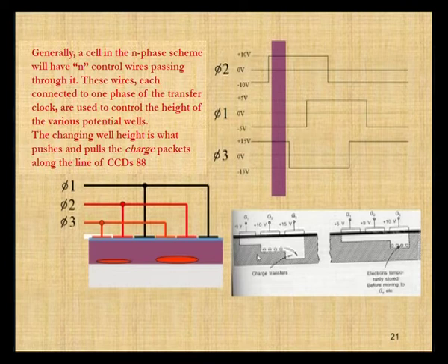The picture also shows clearly how the charge from phase 1 is moved to G2, under phase 2, where the charge is stored, and then it has to move to the next gate, G3. It moves to G3 and is stored here temporarily without losing any quantity or integrity of the charges.